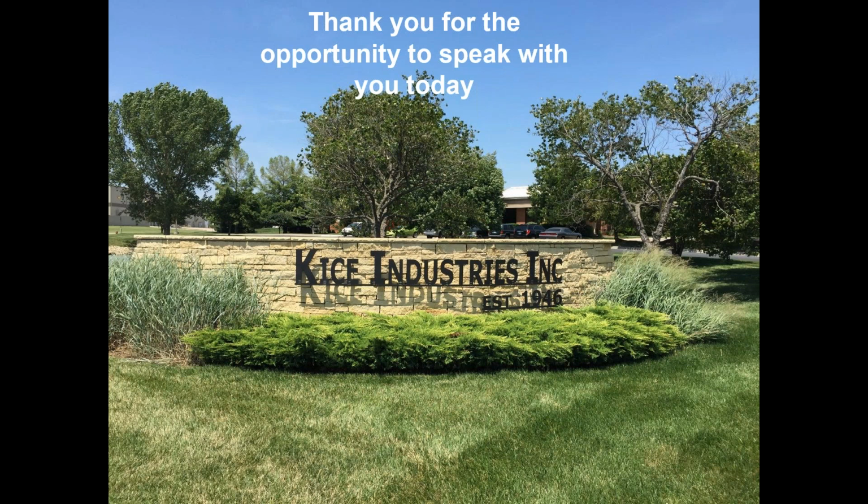So that question comes up a lot, and there are people that have finagled ways to make it kind of work. But in a nutshell, no, it is not a good or effective idea to use plant air or house air to feed a high volume cleaning system.